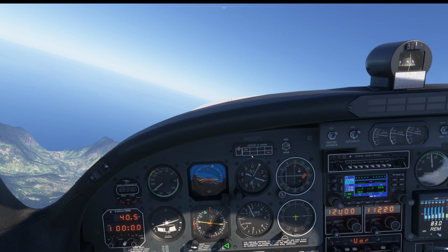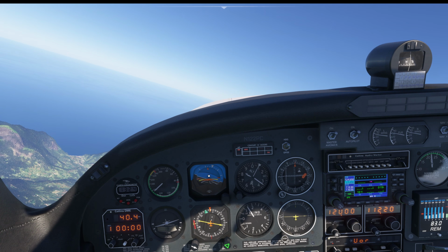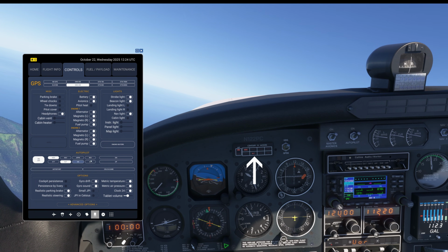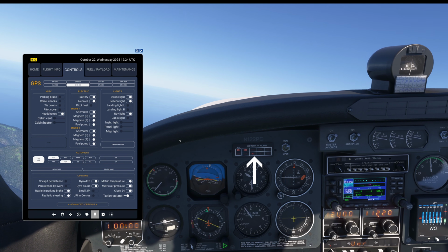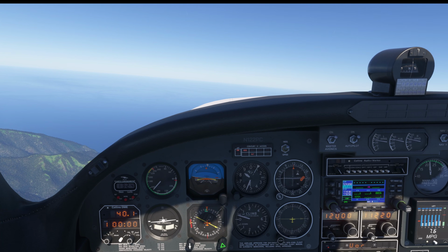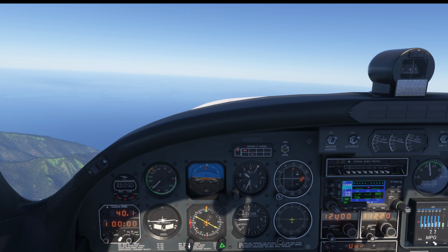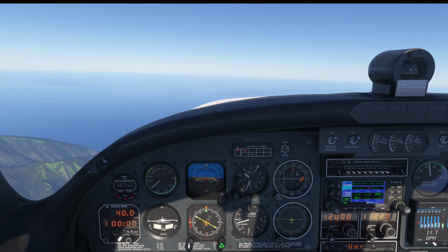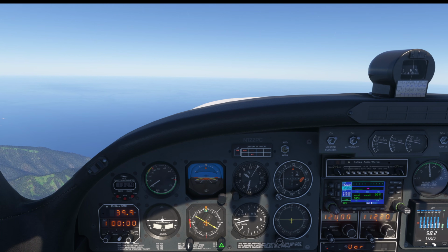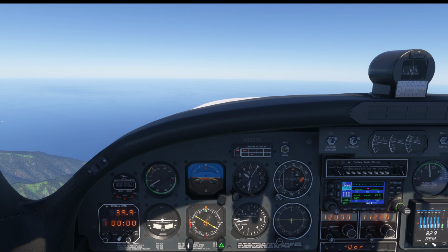Altitude hold mode will hold the current altitude. The autopilot has its own pressure sensor, independent from the cockpit altimeter, and it does not have the ability to pre-select a target altitude. It will simply lock to the pressure altitude that existed at the moment you press the button. That means it's not recommended to press this button if your current vertical speed is higher than 500 feet per minute.